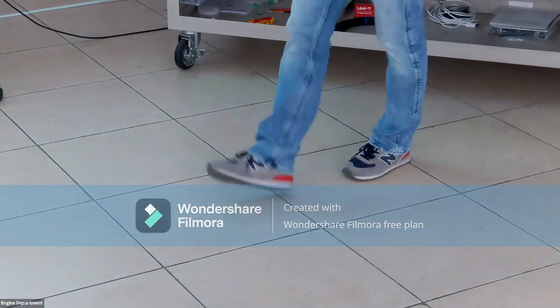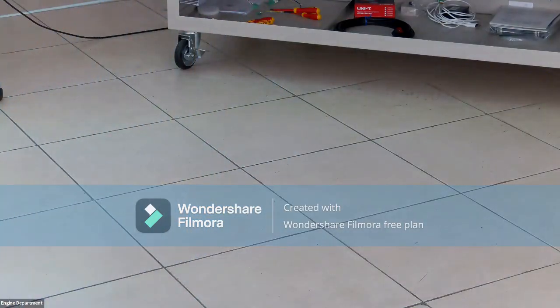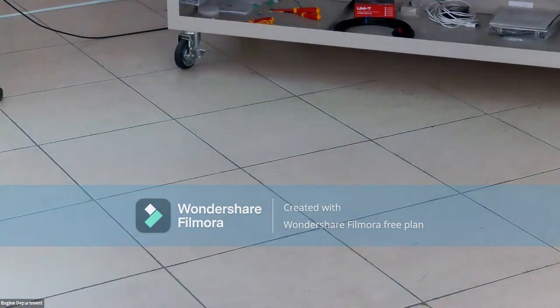At the power supply connection, the LED will start to blink 2 red, 1 green, looking for the server, scanning for the server for around 5 seconds. It will change 2 red to green, downloading the software. And now we have an additional step then, which is required to do then in the new MPC, and this will be identified by LED blinking code 2 red, 3 green.